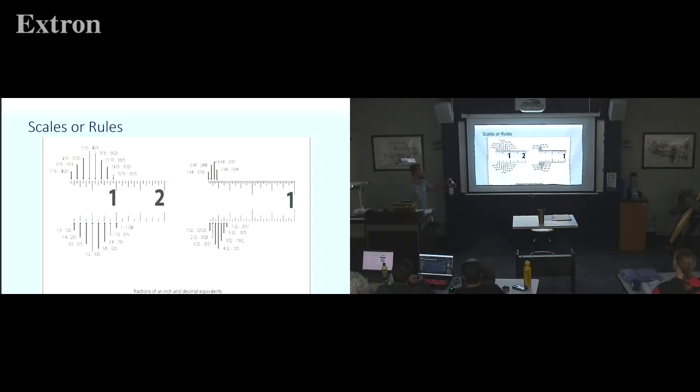All right. So machinist scale, know the scale. So the little ones, it should usually say 1/32 means each little mark is a 32nd. Your machinist scale says 1/64. You got to get out and look because now 1/64 is smaller than 1/32. So you're going to have extra tick marks there. Very, very small. The guide on the back of your machinist scale will be your lifesaver this year. Flip it over, and it already does the conversion for you. Turn it around, it's like, oh, 9/16 is point, what is that? 0.5625 or something like that. Oh man, it's just over a half inch. Yes! 0.5 is half inch. So, hopefully that will be a great benefit to you.